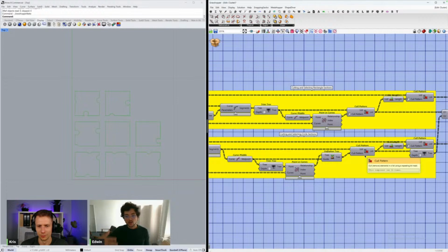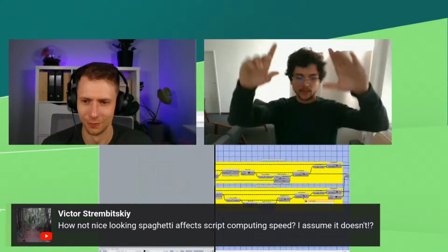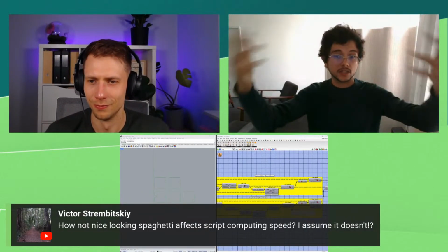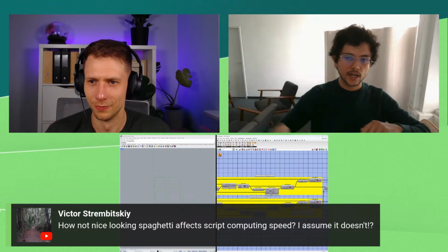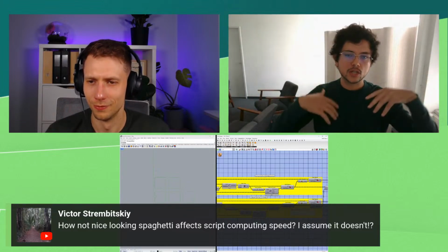And when you open the model, if you have a lot of components, normally the first load takes a lot of time to compute. This becomes an issue when you have thousands of components, which sometimes happens in spaghetti monsters. The issue is that sometimes the Grasshopper developer is not using data trees. For example, you can see from afar, okay, this flow of data looks exactly the same as the one below, and the one below, so basically they are just copy pasting instead of using data trees, or clusters, or other methods to reduce the amount of components that you have.